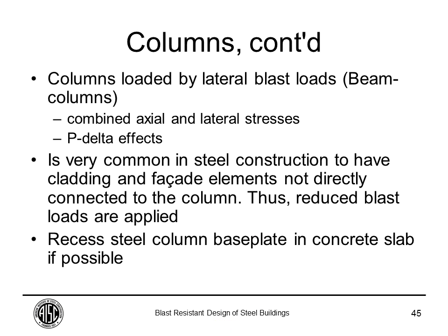The next way a column gets loaded is when it gets loaded by lateral blast loads. And in this case, you're going to have combined axial and lateral loads because the column is obviously carrying axial loads, but now you have the blast load that is pushing on it side to side in the lateral direction.